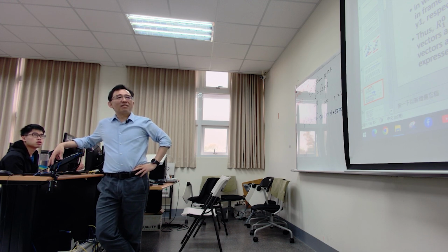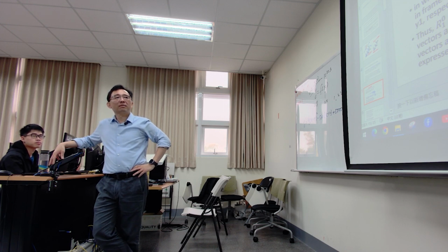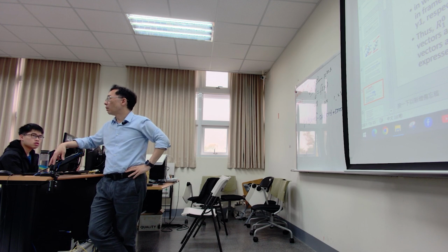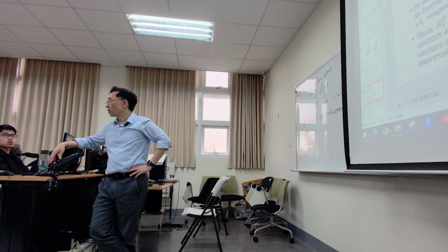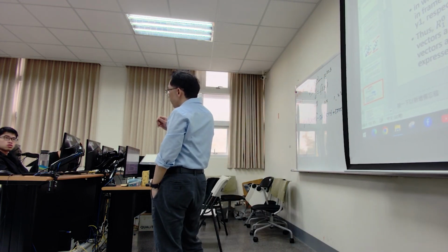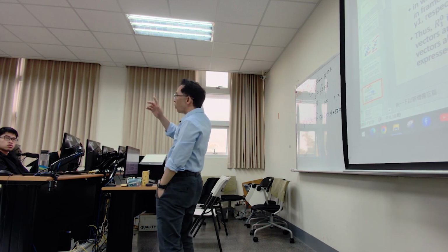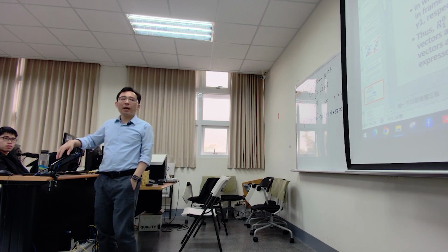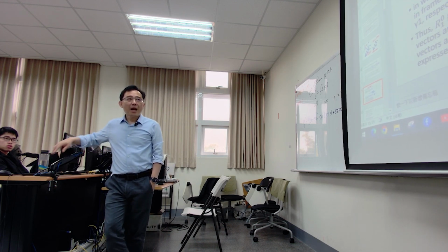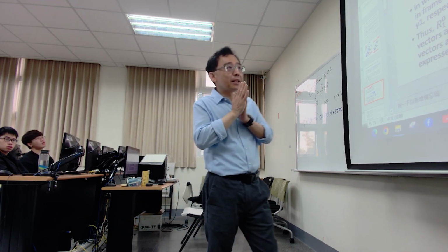Okay, so it's cosine theta and sine theta. The other one is y1. Sorry, y1. So referring back to frame 0, it is minus sine theta and cosine theta. So you exactly know where it came from, right? No worry. If you know the inner product and this is a unit vector, so there's no amplitude in front, only the trigonometric part is left, and then you'll be fine. And combine it together, that's the magical term.